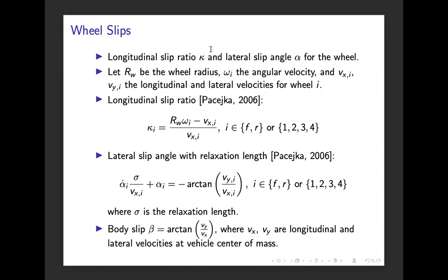Ideally we would have quite low slip, so that what we deliver in terms of power to rotate the wheel will be quite close to the velocity that we actually have of the wheel. So this is a description of the longitudinal slip ratio. How much is the wheel spinning in relation to the actual velocity of the wheel? This is a very important variable to control for vehicles.